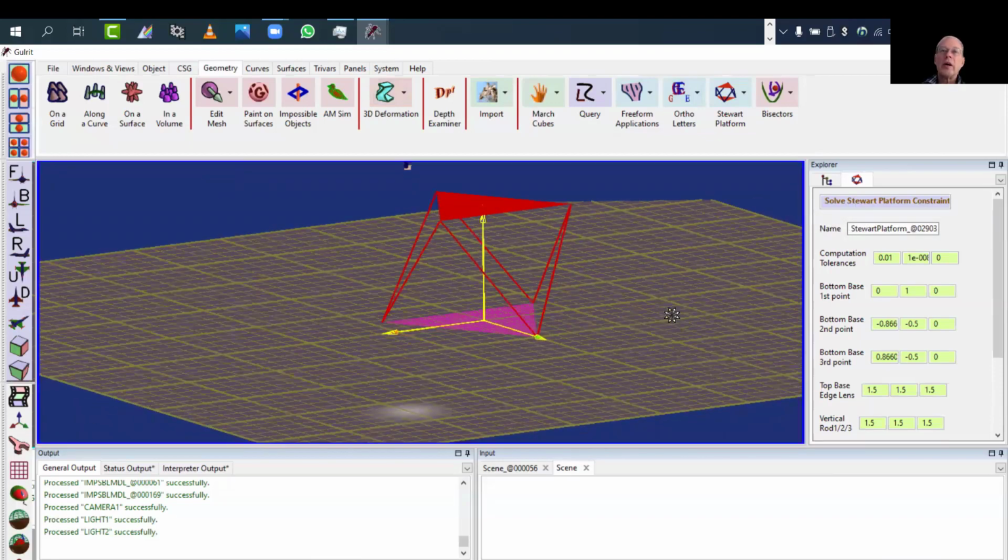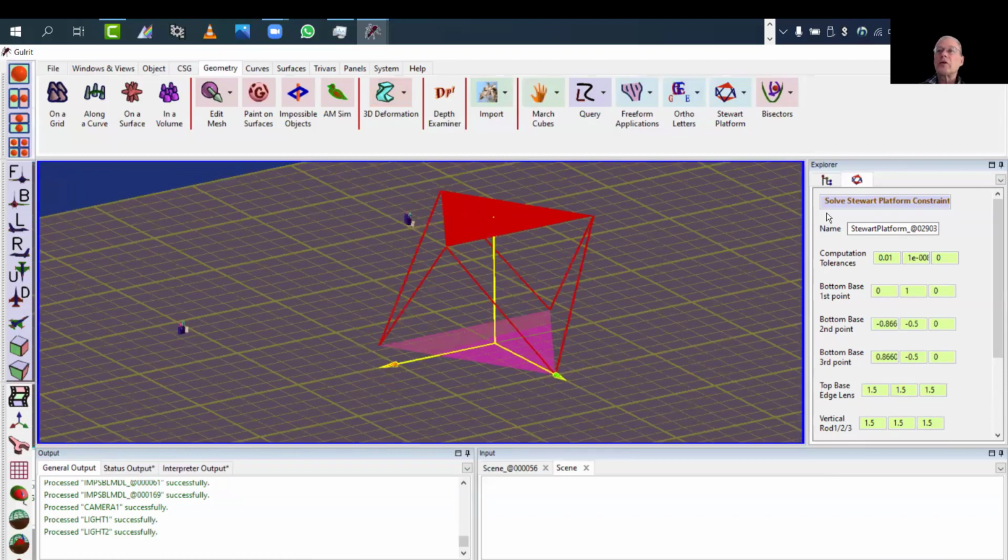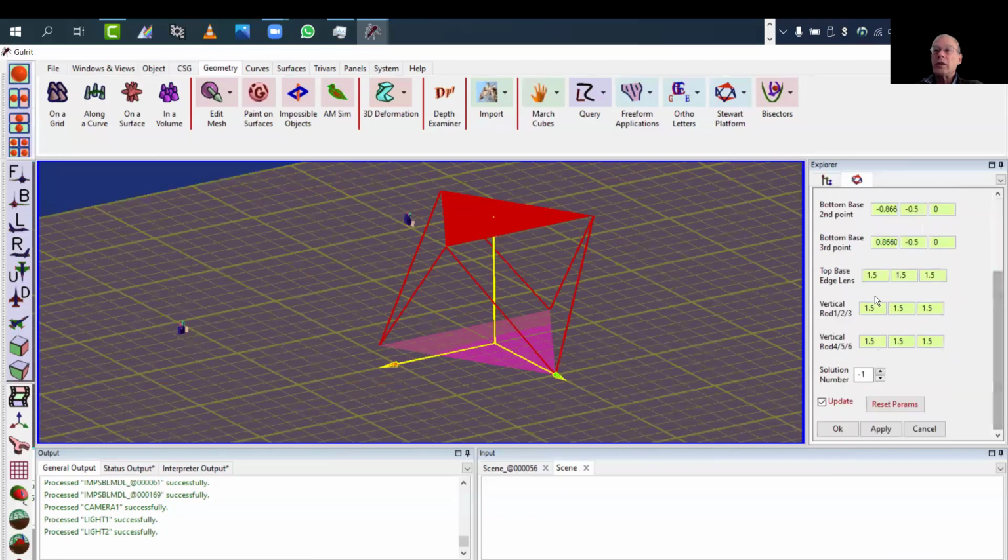You will see that. Anyway, the Stewart platform is a robot that has a stationary plate here and a movable plate there. And the movable plate is controlled via 6 rods that you see over here. And these 6 rods change length. So by changing length, and I have 6 rods, I have 6 degrees of freedom. In fact, I can create all the expected degrees of freedom of rotation and translation. And you can see it here.